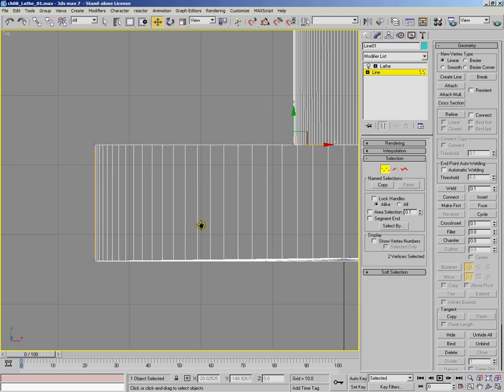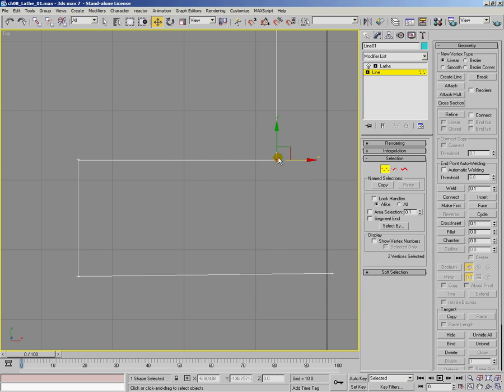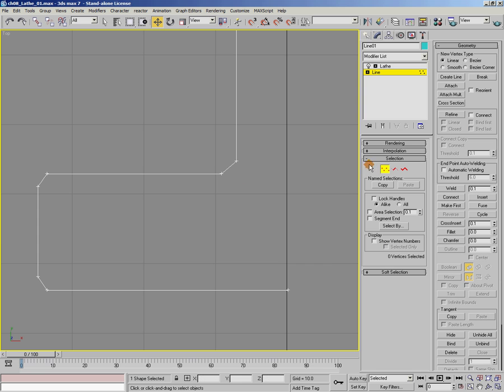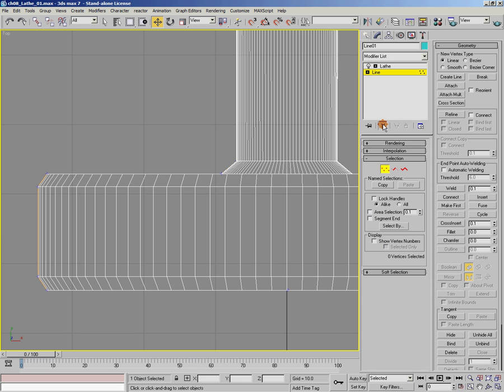And let's say this is a little crude, which it actually is. We could put some bevels on here very easily. Just refine this. This is the great joy of working with splines, is that you can just go in afterwards and refine things and make it a little bit better if you think it's a little bit crude. So we can just move this up here, grab these, move these down, move this in a bit. It's not quite the same kind of dimension as you have over here. And then we can just select all of these, right click, change to Bezier corner, and then we could leave them as corners if we wanted to, and we'd end up with this as the result, as you can see.